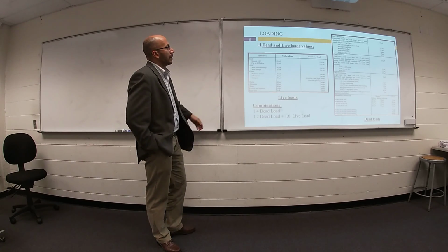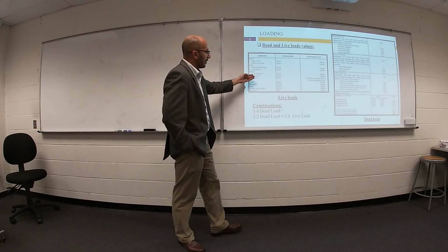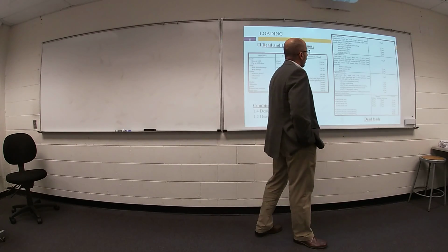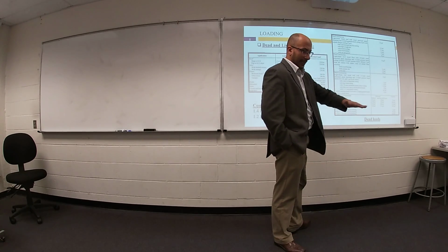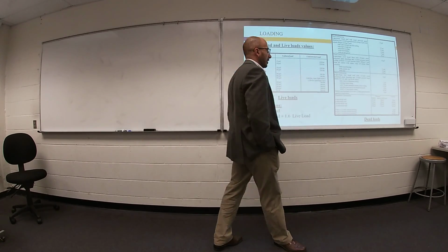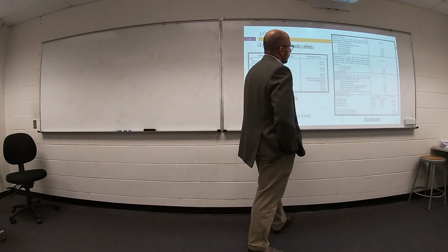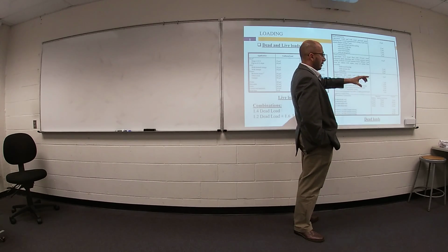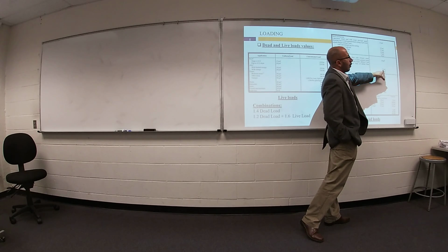So based on the main purpose of your structure, I can figure out the value of live load. Also, I can figure out the value of your finishing, ground or floor finishing. So for example, if your finishing is wood flooring, this finishing will cause an additional dead load equal to 12 pounds per square foot.